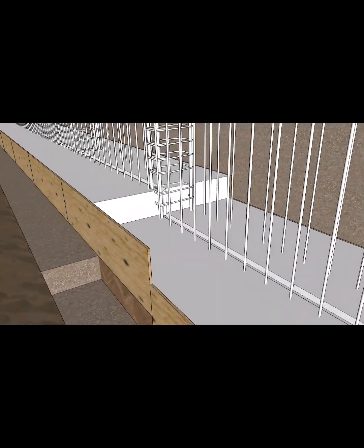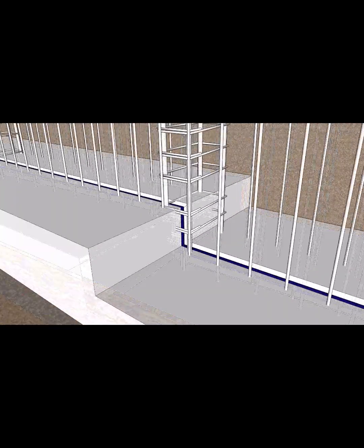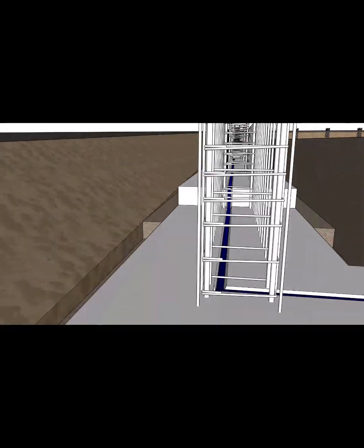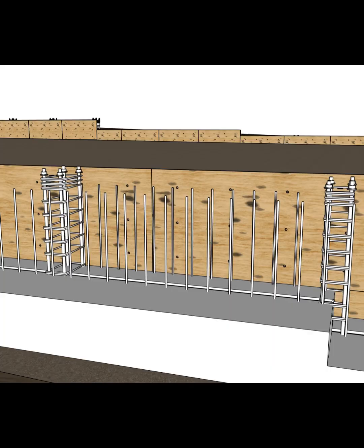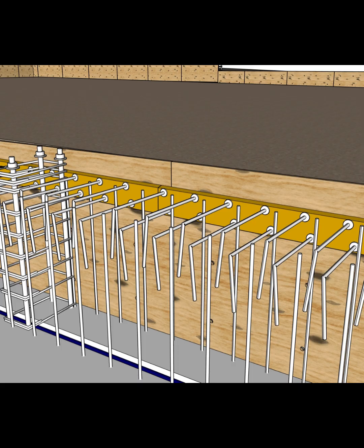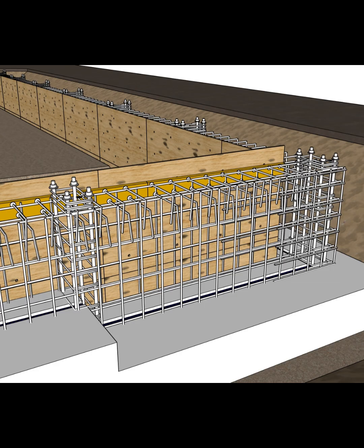Pull the keyway and install water stop. Install the interior wall forms. This sequence is important because we are using form savers and attaching them to the interior wall. Interior wall forms set firmly with snap ties at the bottom 2 rows, whalers, strong backs, and aligners. Set elevation on form wall and install chamfer. Install the keyway with attached form savers. Attach the plinth cages to the formed wall. Install any additional snap ties.